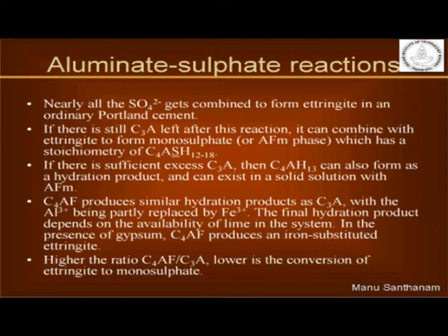Now why is this sulfate resistant cement actually resistant to sulfates? Because when external sulfates come into this system, the ettringite is already stable in that system, so it does not react. But when the sulfates come into a normal Portland cement system, the sulfate will react with monosulfate and convert it back to ettringite. Now this conversion is happening when the concrete is already hard.